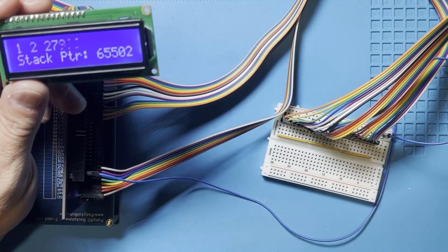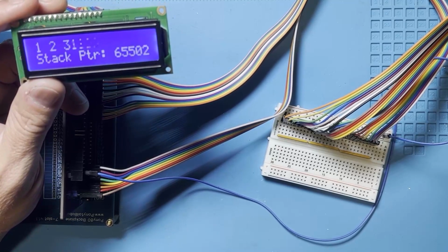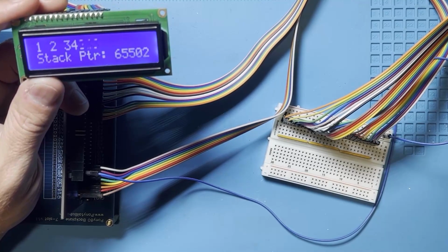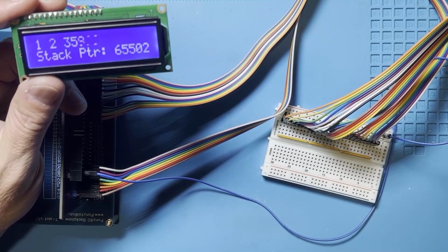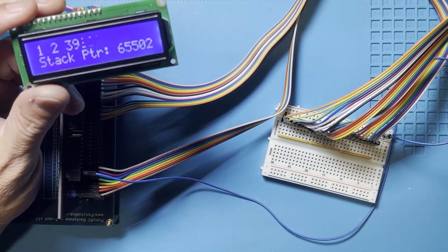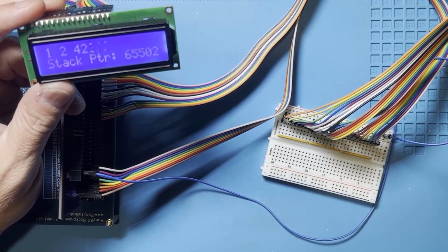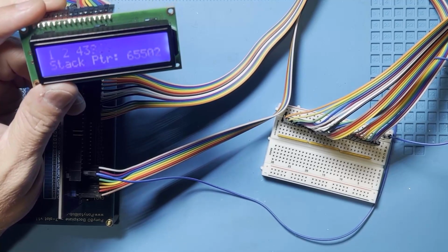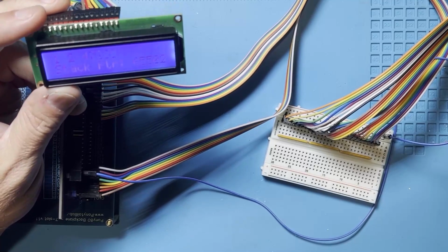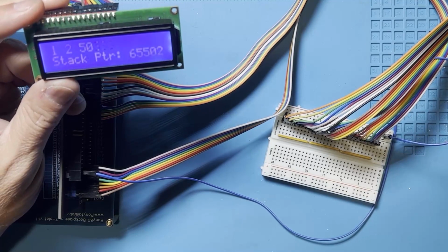I'll give you some heads up. So the mode 0, it works just like the Intel 8088, or is it 8080? One of those two, that it was replacing. And the reason why they did that, it was so that they had that market backward compatibility, and they could just use the Z80 the same way. It's the same thing with the instruction set. The Z80 is backward compatible to the 8080, or 8008. It's one of those 8 numbers. There's 8s and 0s in there somewhere. It is backwards compatible, and that's what mode 0 was for.